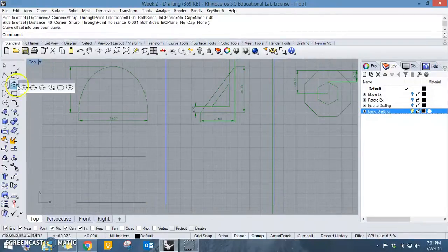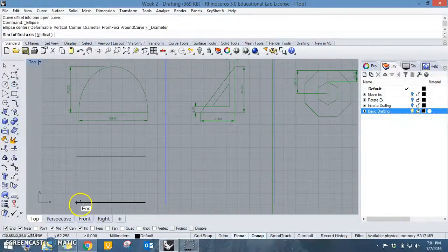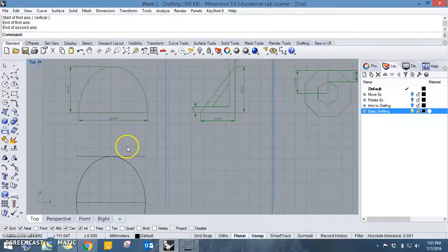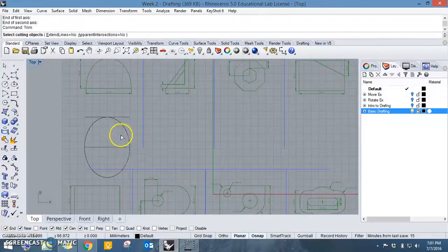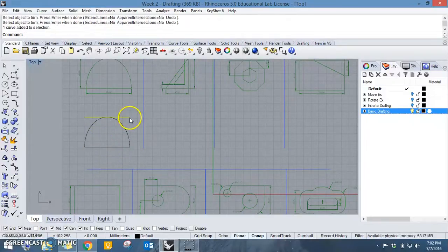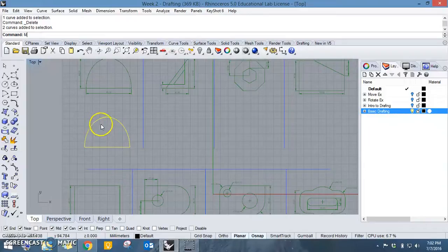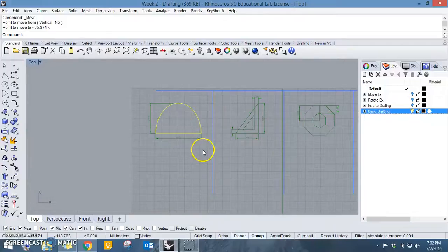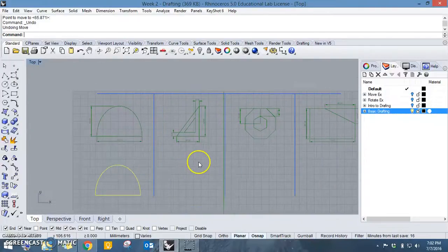Once that's done, we click the ellipse, select the diameter, meaning end to end, and then we can draw the ellipse. We select the end, the second one there, select the end, and select the height. Select the mid. Next we can trim it. We select, we trim. We can remove this, select both. Let's just move it and check. Okay, undo to put it back in place.